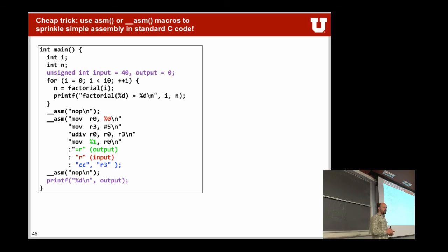And one last thing, if you really need to add assembly into your C code, there's a small little trick that you can use with the statement __asm that will execute assembly code. It's a little bit tricky how the notation is, because imagine that the problem now is you have assembly code and C code. You have them work together. So you somehow have to tell the assembler what your input is and what you get out from your assembler code. Because in assembly you don't have variables, really. You have registers. But in C code you now have variables. But you don't really know where all these variables are stored at which point in time.